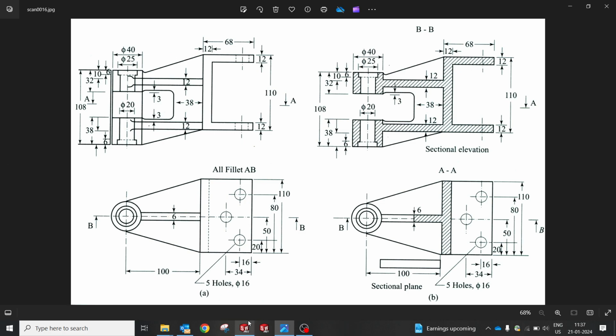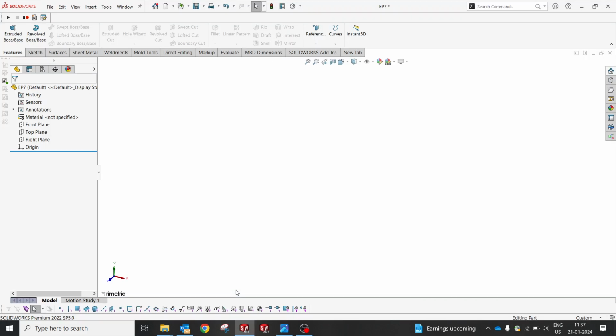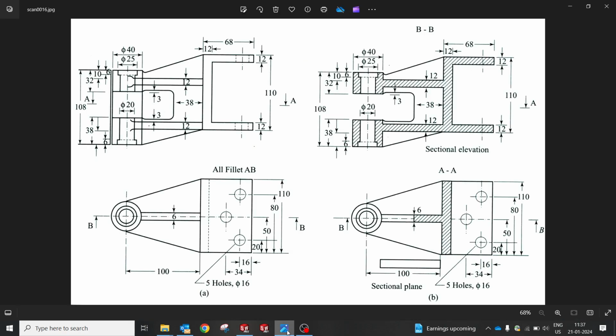Let me open Solidworks, and here we are. Let me explain before: I'm gonna create a revolve, and then an extrude by selecting a mid plane, and then I'm gonna create a rib feature of the other three. So there are two main views: this is a side view, and this is a top view where we made a section of AA and also a BB section over here.